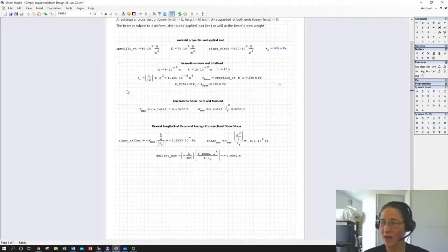You start with your beam length, its cross-sectional shape, understand the material properties that will be important, understand that in the case of a beam with simple loading, we're not twisting the beam, we're not giving it any side loads. You have three types of stresses you'll worry about, and basically strains, deflection. So you'll have longitudinal deflection, you'll have shear stress, longitudinal stress. You're designing against yield or maximum displacement for those.